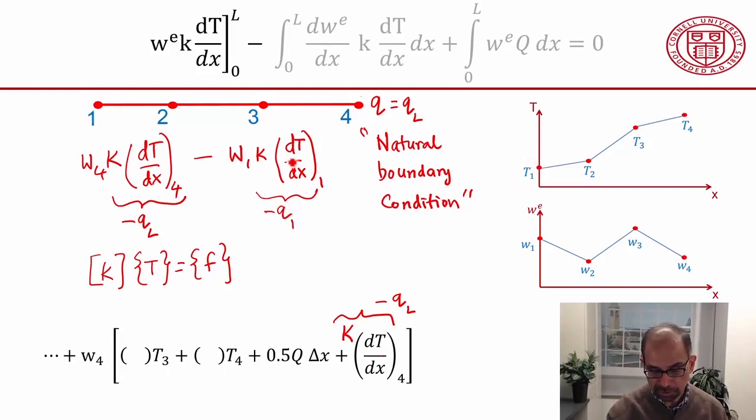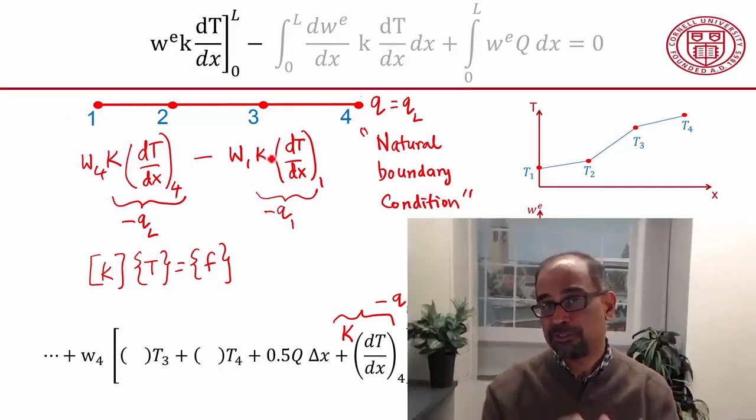So it's giving you the flux at this boundary, and that's not known. What's done is you use that term to evaluate the flux at the left boundary, and then you can use that to check energy balance. And in ANSYS, when we compute a reaction, that comes from a term like that, and we will look at that a little bit later, because it's a very important way of checking your results, whether it's conservation of energy in this case, or when we go into structural mechanics, equilibrium.